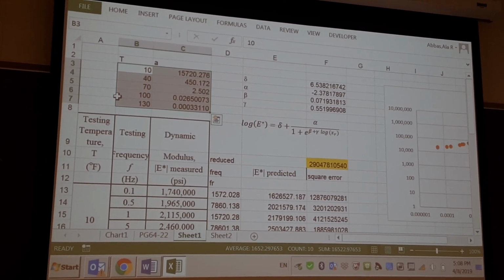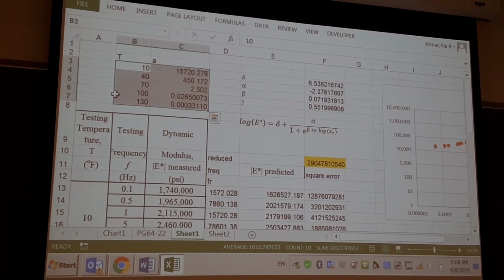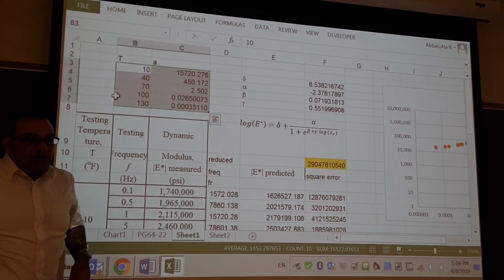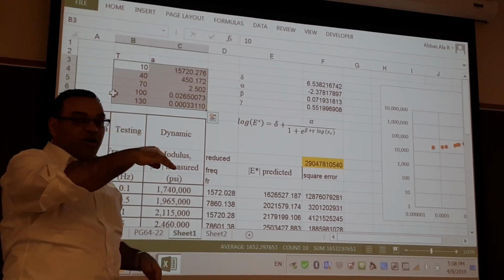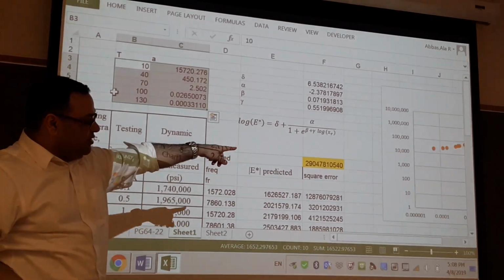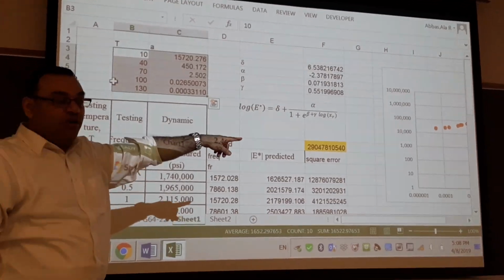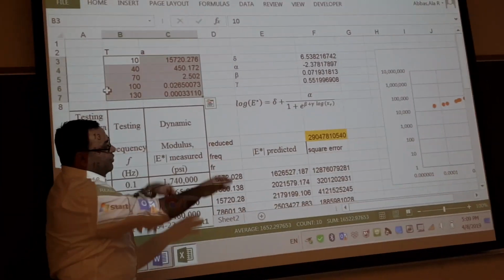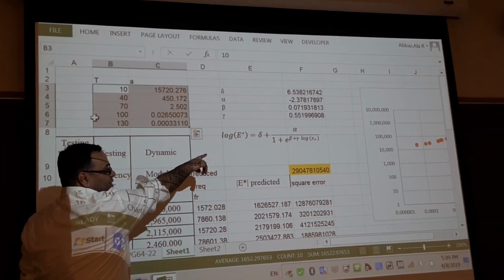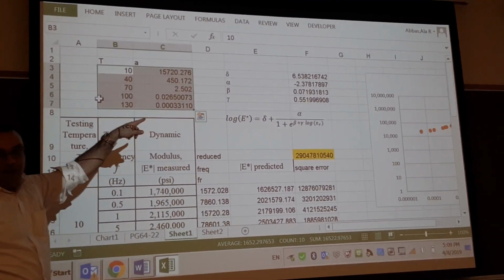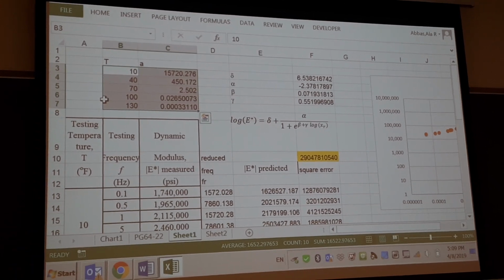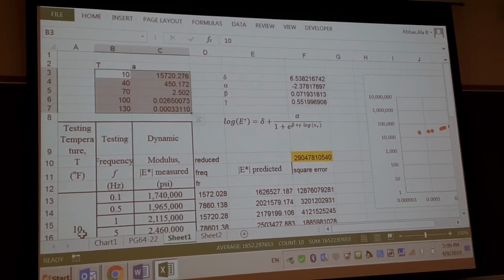Okay, so to be able to get the stiffness of the asphalt mixture, the stiffness of the asphalt mixture is dependent on two things, yes? It's dependent on the frequency, like we can see in that figure, but it's also dependent on the temperature. The frequency is captured using the sigmoidal function. For the shift factor, we can develop another model to actually describe that relationship. Now to do that, this is the model that you need to use.